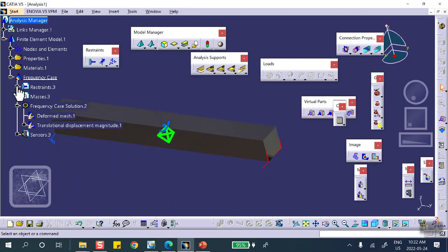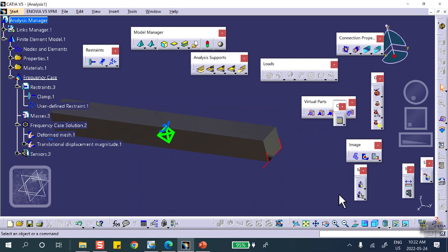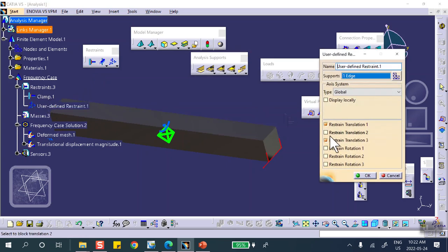Go to that restraint. Instead of a roller here, basically, we call it a roller, but don't confuse it with surface slider. It's not a surface slider. I delete this, either delete it, make it a clamp, or I can also go here and make this thing all 3 degrees of freedom. That is the same as a clamp. For a solid element, that's the same as clamp. No translation X, Y, Z. I'll leave it like this, okay?